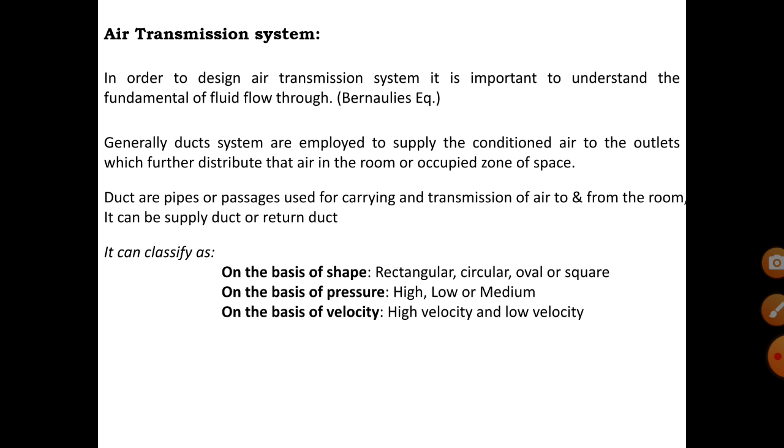So this air at 70% RH consists of some moisture, some water particles, water molecules, and the temperature of condensation, that is the DPT, dew point temperature, would be around 20 degrees Celsius. When it reaches that, the hot humid air starts condensing. As it condenses, it forms a layer of water on the outside surface of the duct, and that water collected on the duct comes in contact with the wall and discolors the wall.